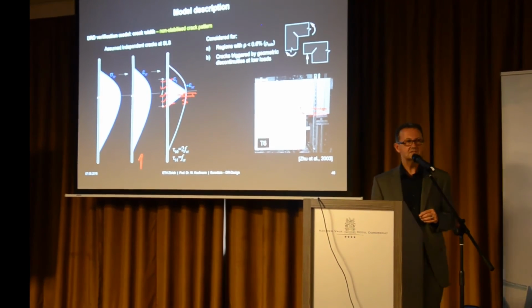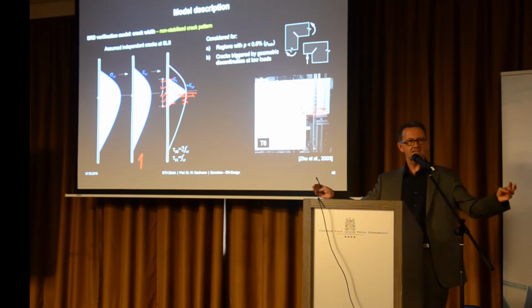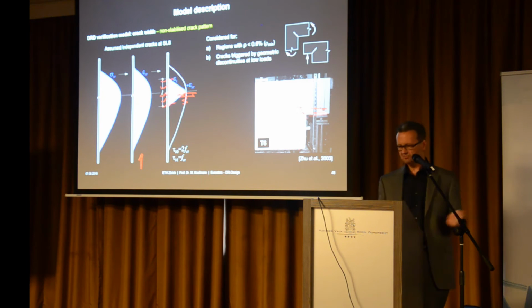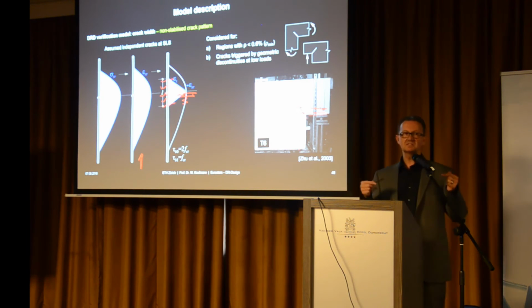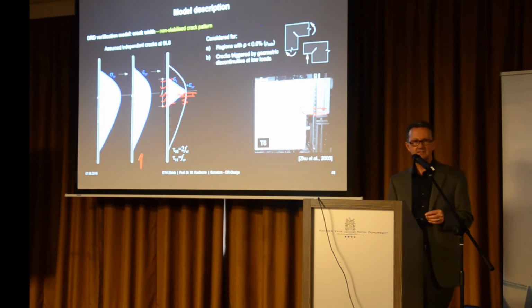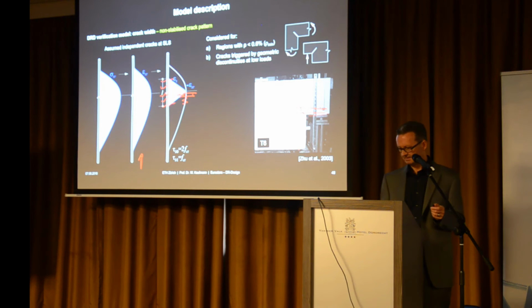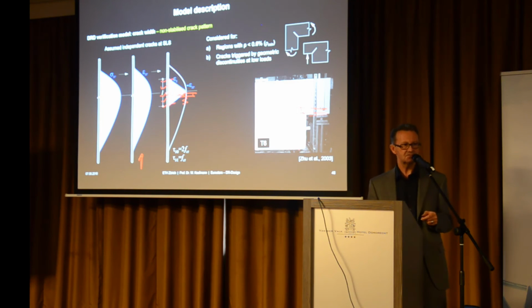What we're doing is we're integrating over the entire length that this rebar will be activated if it's pulled out, even if we're above minimum reinforcement in this situation. And that gives us higher values for the crack opening. It's important because we always got too small crack openings in these tapered end beams, and we did not want to provide you with unsafe results.